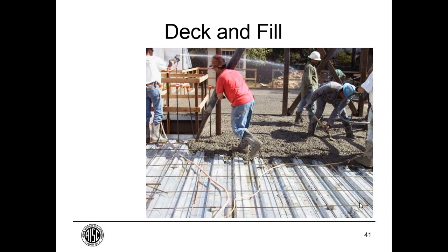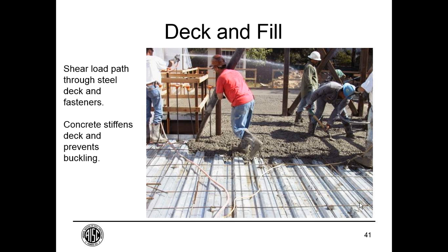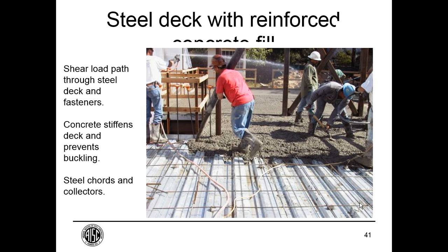That deck can be stiffened with a concrete fill, and again, the shear has to be in the deck and transmitted through the fasteners, whether they be welds, or here studs or screws or shot pins. The strength of the steel deck itself is increased by having the concrete fill to stiffen and prevent buckling. However, the mass is significantly increased also, and so the shear demands are much larger. And again, the steel framing is used as chords and collectors.